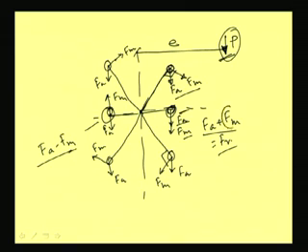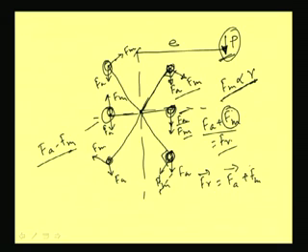Again this Fm depends on the distance of the rivet from the CG. Fm generally varies with the distance between the CG and the rivet. So, naturally the corner rivets will exert more force due to moment, because of more distance, r is more. So, in this case also, for this rivet the resultant force will be like this. So, Fr will basically be Fa plus Fm.